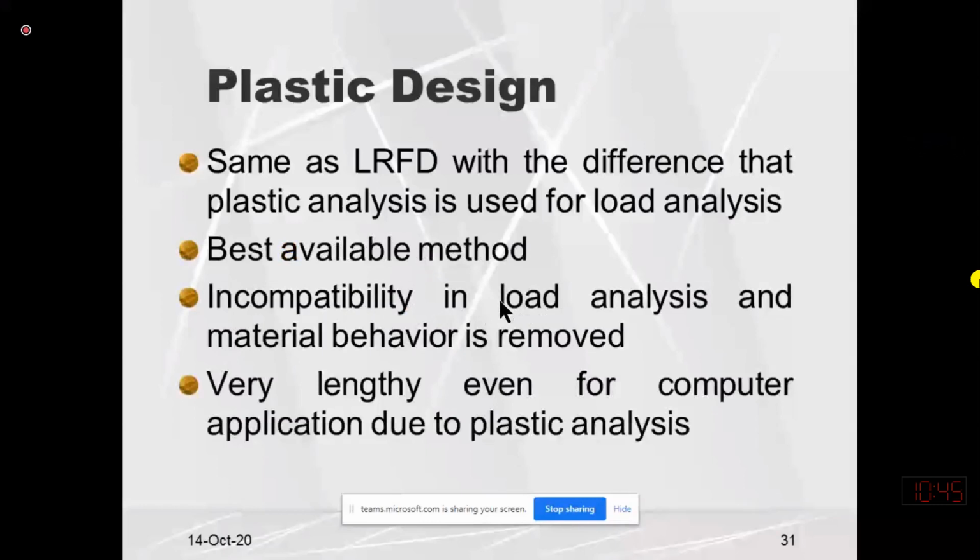If I consider material strength more than or equal to the yield value, then the LRFD method will be referred to as plastic design. So it is the same as LRFD, with the difference that plastic analysis is used for the load analysis. Plastic analysis you will study maybe in structure analysis. So this is the best available method. Here we are considering the actual failure behavior in design and analysis, so we can compare both methods. So the incompatibility between load analysis and material behavior is removed because we actually know what type of failure occurs. So based upon the failure, we design with that method.